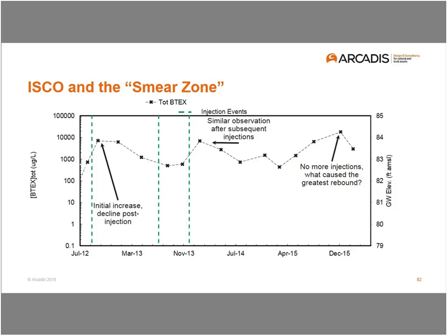In the first injection on the far left, we see an initial increase in concentrations, almost an order of magnitude increase post-injection. Now that can be okay if you see it after the first injection and it's the residual LNAPL that's been dissolved and you've tapped into the resource, so not unexpected. So 2 following injections were staggered out to maximize that rebound, right?